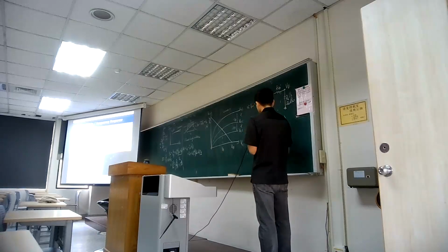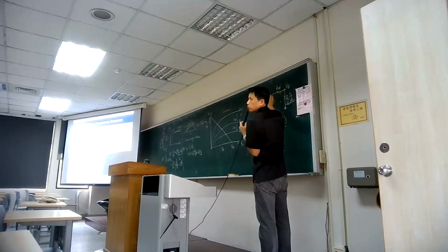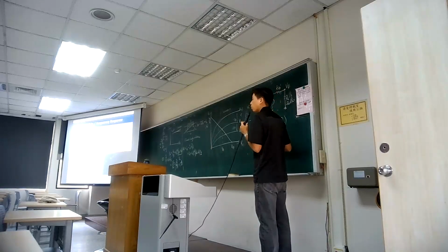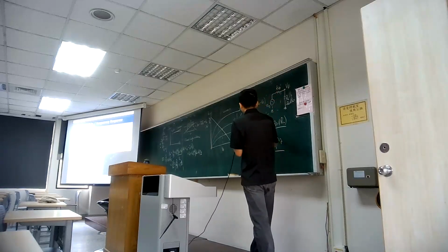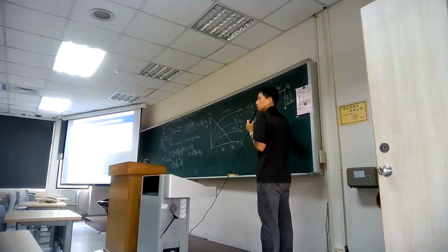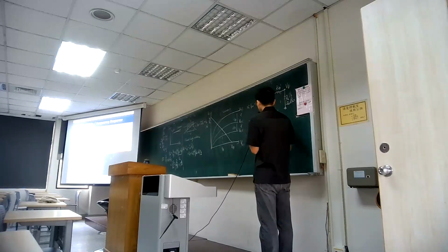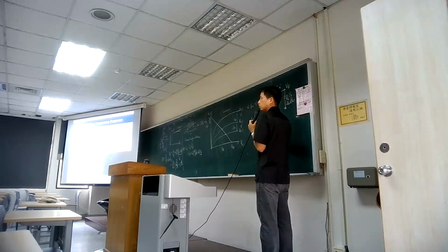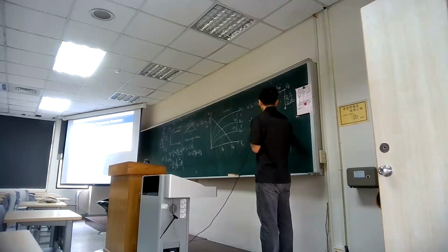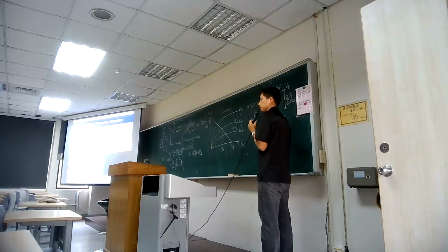So it is a good benefit for you. If RG is large, the resistance in the function generator can be ignored. And then we can determine how we amplify this one. The resistance in parallel is determined by the lowest resistance, so it depends on RD or RL, because RO is typically large. RD is used to support your voltage, so RD is on the order of kilo ohm. So the question is, what is the load impedance?